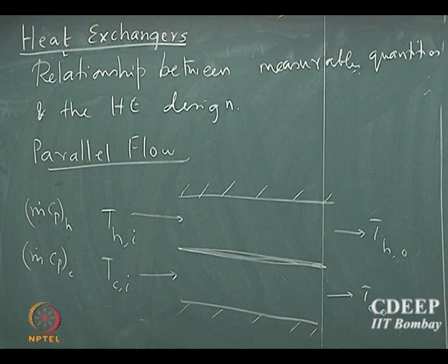Something called a Peclet number, which characterizes the time scale for dispersion and the time scale for convection. And so, depending upon the Peclet number, one could actually discern as to when the axial conduction or axial thermal dispersion is important. Okay. So, really it means when axial thermal dispersion is important, and then we assume a steady state and constant property.